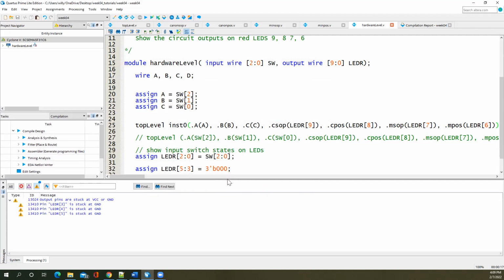And no error messages, right? In some versions of Quartus, it will put a message here saying it successfully imported the pin assignments. Other times you don't get that message, right? What we need to do now is that we've imported the pin assignments, right?